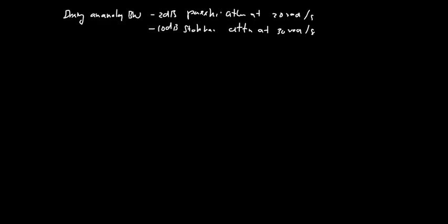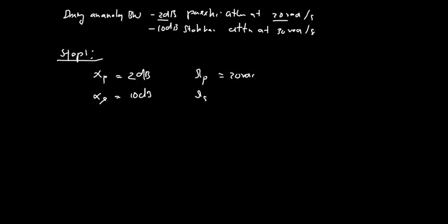Okay, now with respect to this problem, step 1, what we have seen in the last session: you need to find the alpha p, alpha s, and omega p and omega s. So in this challenge everything is given very explicitly. This is my pass band attenuation because it's a lower frequency, so 2 dB, and alpha s is 10 dB, omega p is 20 radians per second, and omega s is 30 radians per second.